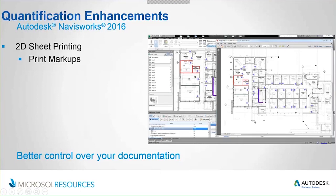It's actually interesting. Navisworks in the past really wasn't much of a quantification tool, but with the integration of QTO into Navisworks, you're going to be able to do a lot of estimating, a lot of takeoff, both from your model as well as two-dimensional. I think the model takeoff is the more intelligent way of addressing quantification, being that all your geometry is generated in Revit. I'm going to be able to quantify all the individual objects. If you're really interested in doing two-dimensional quantification, again, take a look at Bluebeam, and we'll do a comparison between the features that you see here in Navisworks against the features that are available in Bluebeam.